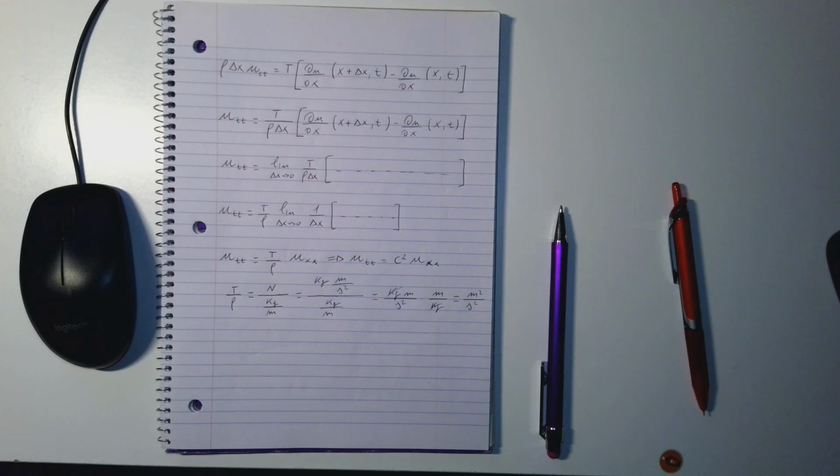It depends. You can have different, and this is what we are going to talk about now actually. So when you look at continuous systems, you can have fixed supports or movable supports, or you can have supports on strings. You can have supports on springs. So this is something that will have an influence on your final solution, because if you change the support, what you change is the initial condition, basically.